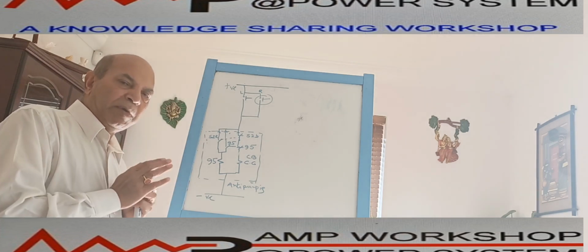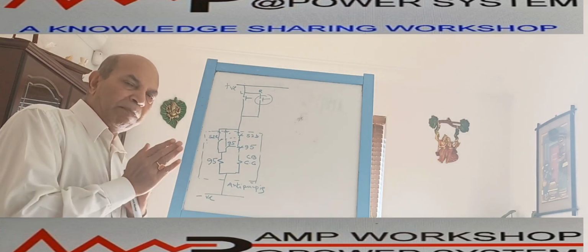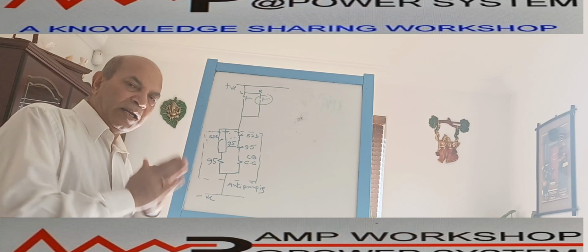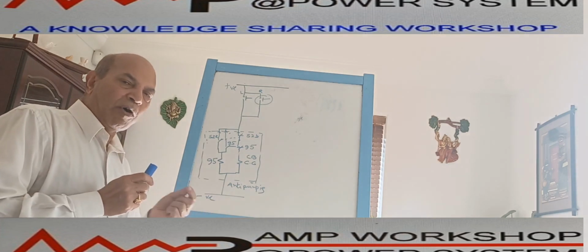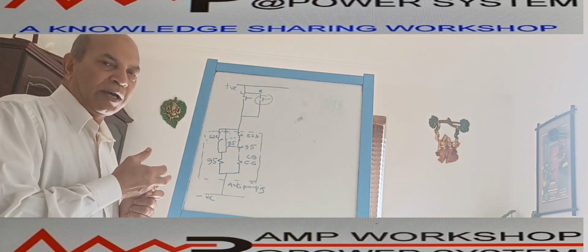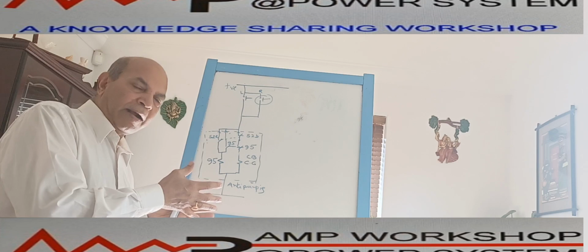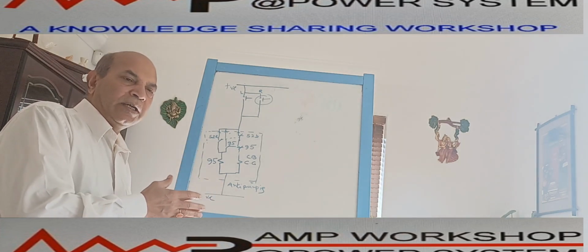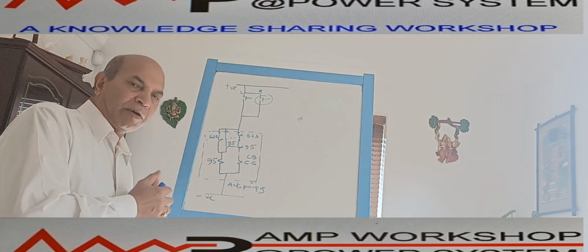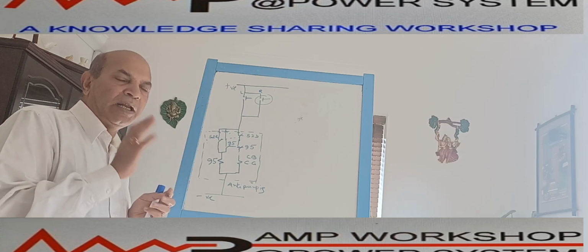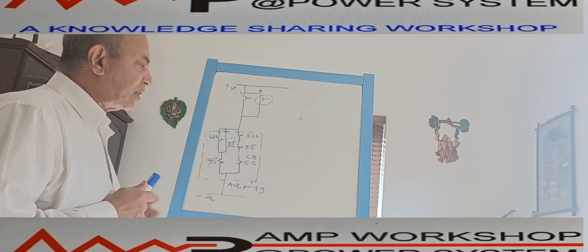The plug has multiple pins; when I put the male part of the pin inside the circuit breaker body, it gets engaged, and on the back side of the plug the wires are connected. So you cannot get access if there is some problem with this device in the breaker, or with the arrangement preventing the continuous command. Then you need to open the breaker chamber, which is difficult. These are all connected through pins, and only the pins are accessible. We will discuss that separately.